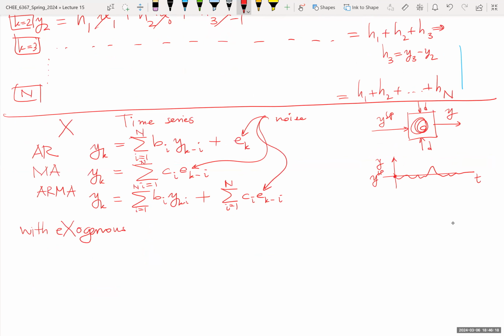And of course, you may have the autoregressive integrated moving average model, because remember, all of these are stable. There is never anything going to infinity. Well, in practice, for many processes, things may drift slowly to infinity. So it's not a blow up, but it's not a return to steady state. This I basically says that I'm integrating something. So the general form is just like ARMA, so yk is the same as above.